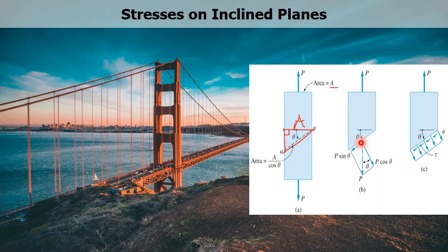This perpendicular force is equal to P cosine theta. Kung saan nakakabit si theta, siya ang magko-cosine. That's why this is P cosine theta, the normal or perpendicular force, and this is equal to P sine theta, the shear or parallel force to the inclined plane.